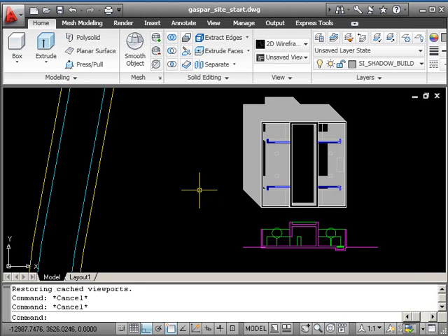Stay in this same drawing for the next little demonstration, and that's to do with contours. We're just going to put on some totally made up contours here and show you a wee bit about those. They're often missed off drawings, and they can tell quite a bit about how a building works, how the approach to a building works, which areas are going to be flat in relation to the building, which areas are sloping. And it doesn't take long to add some of this information back onto a drawing. They're essential when we start a drawing, but we seem to forget that they exist and never seem to show them on the final drawings.